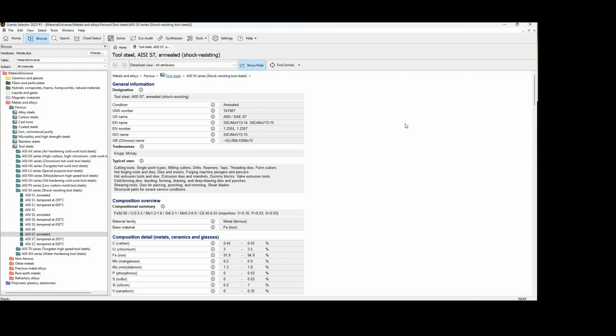Down here we can see how much carbon it has, how much chromium, iron, and you can see sulfur, silicon, everything is the percentage of that. And again, as you can see, it's the range. We don't provide you exactly because each vendor can do it differently. So Tata Steel may do it different from your Chinese vendor that you have. But we have reviewed what they're offering based on the handbook, and we give you that range here.